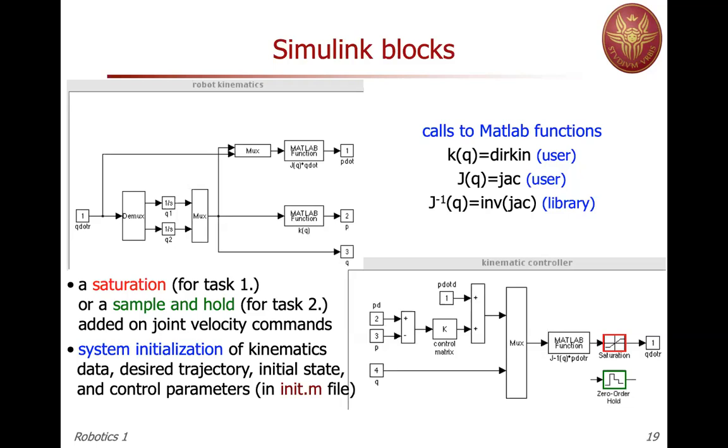Okay. Now remember that when you do a simulation, a Simulink diagram, so this is a practical recommendation, but very important. Never put numbers into the blocks. Use always symbols. If you have a length, use L1, L2, and define the numerical value of L1, L2 in a separate MATLAB file from which you initialize all the data, and you can also run the Simulink block without opening it.